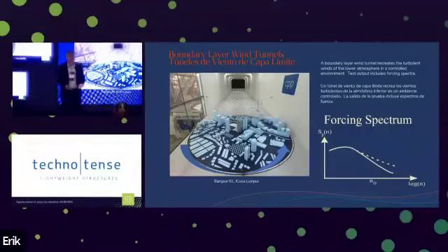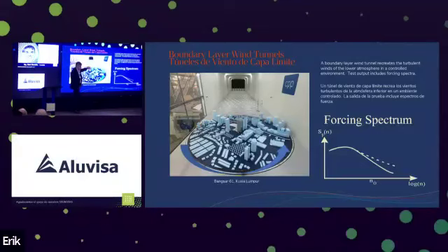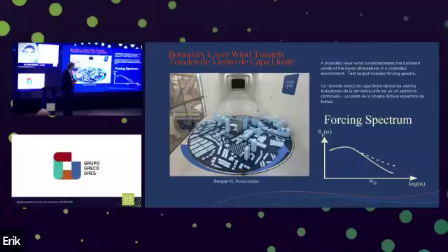The profile varies in velocity and turbulence intensity according to codified profiles. And importantly, there's a spectrum of turbulence that we simulate in the wind tunnel. That generic profile gets modified across the turntable of the actual surrounds, so that by the time the wind hits the subject building, we're simulating the actual wind forces it's going to see in real life, but at scale.